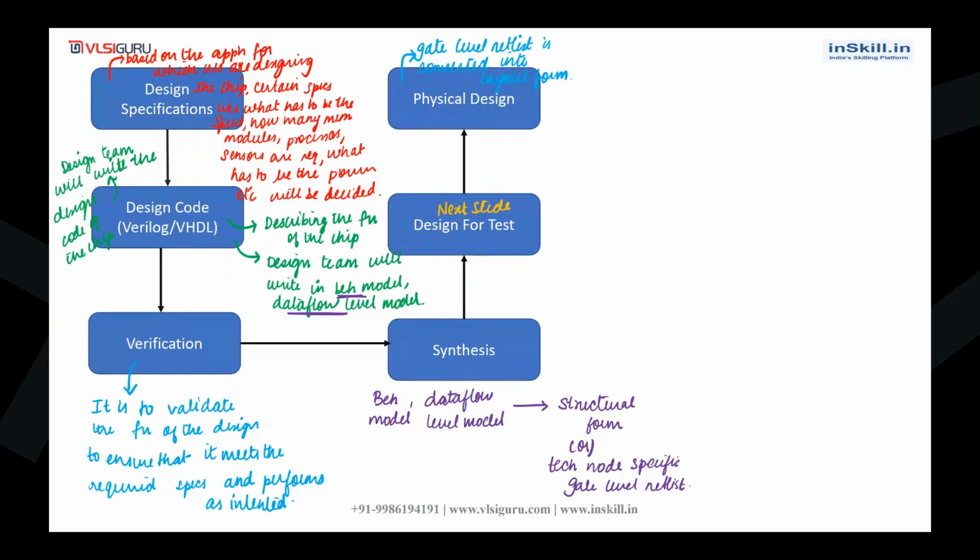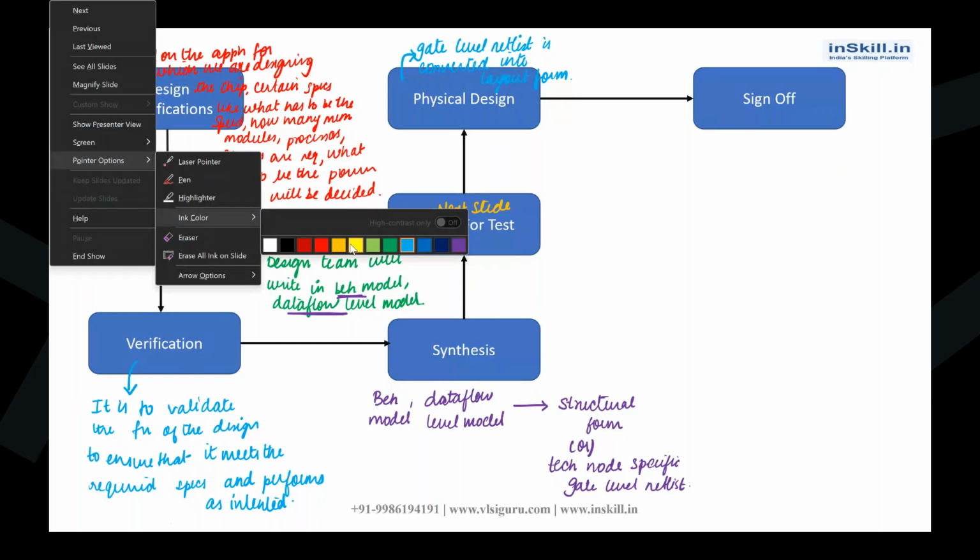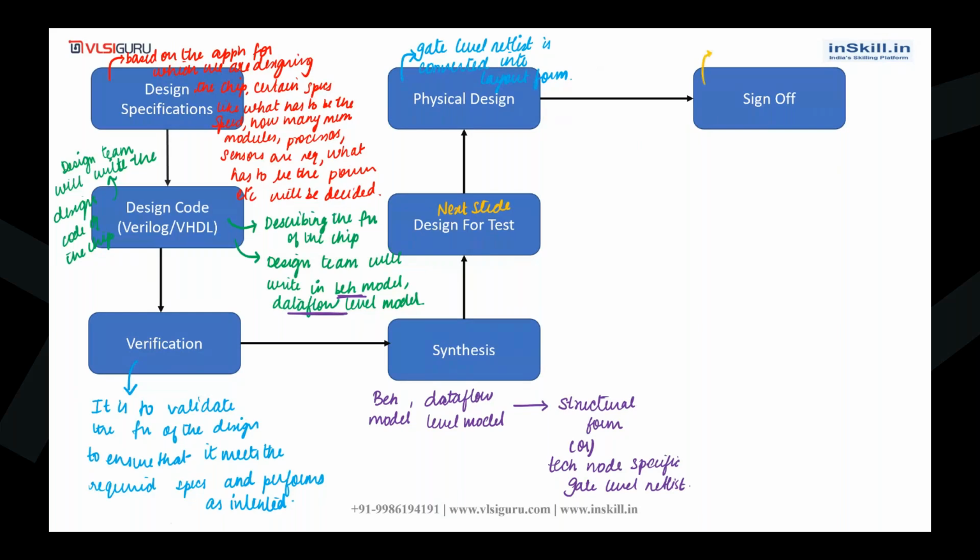Okay, and after this, we have sign off. So in sign off, we have three things. One is STA, static timing analysis, then physical verification, PV, and then logical equivalence check, LEC.